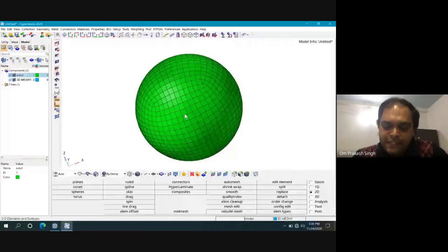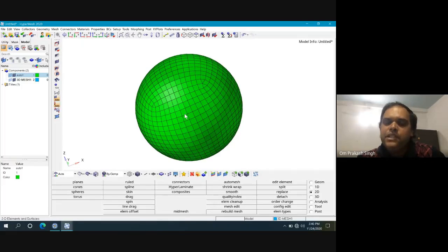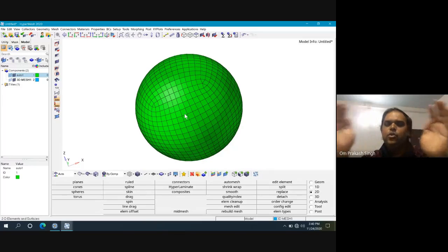And to do CFD, your first target should be, when your mesh is generated, it has to be a closed surface, irrespective of what kind of CFD you do. You can go to, let's say, flow over a car, flow over an aeroplane, or a nanofluid, phase change material. When you do CFD, it deals with a closed volume.